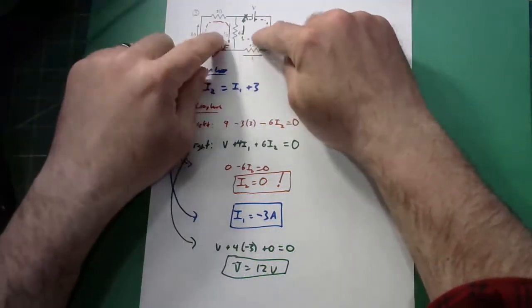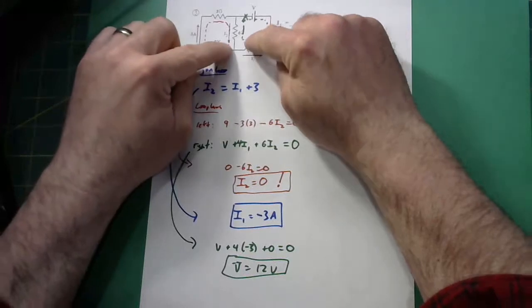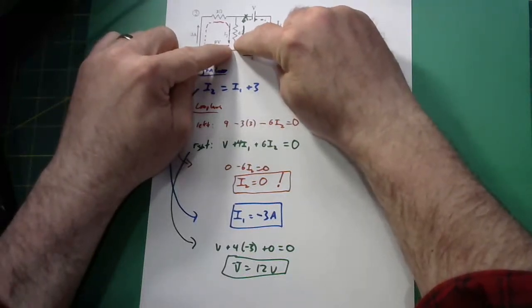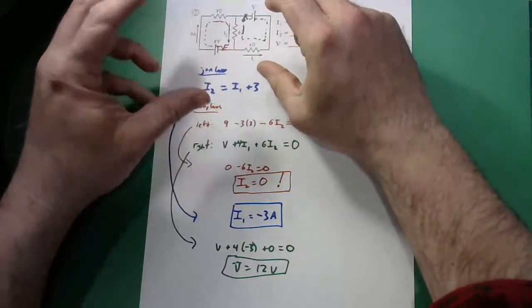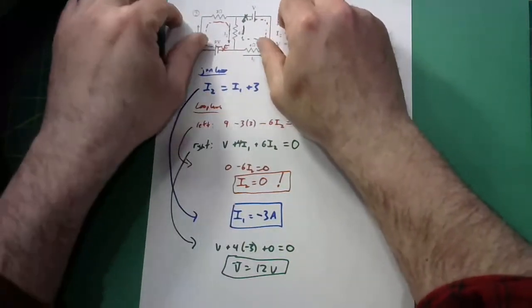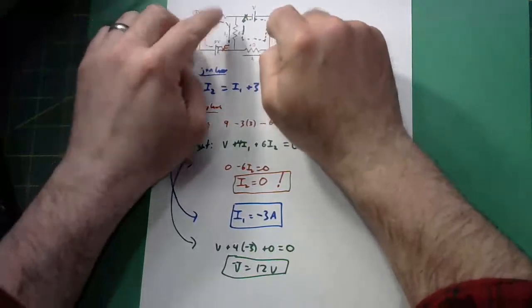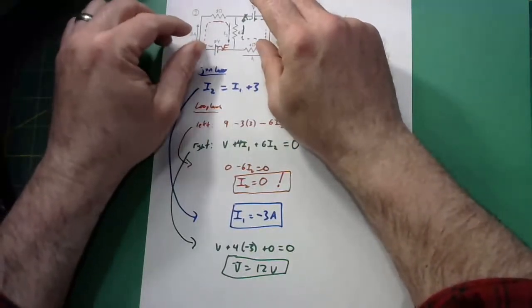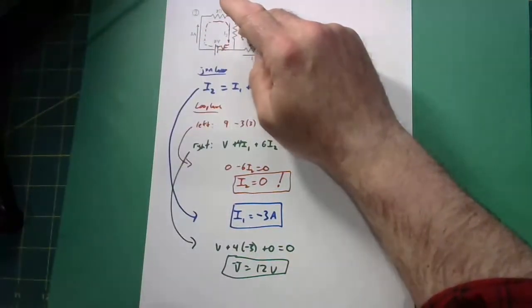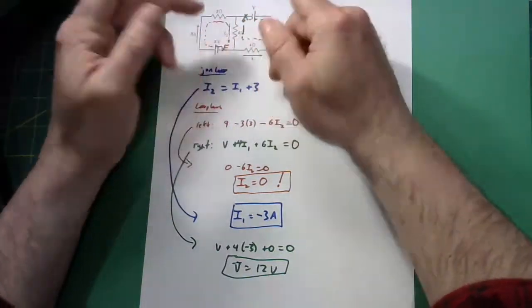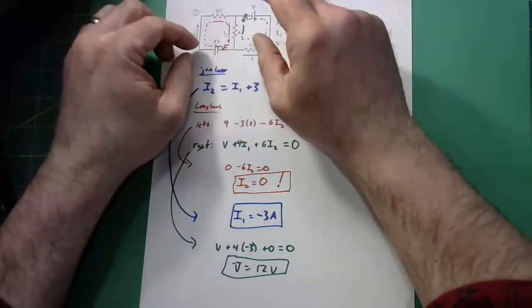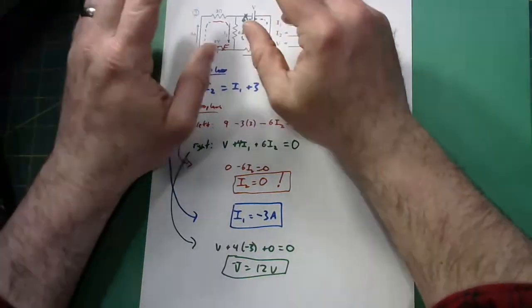So this is not a good example, but basically I'll have an ammeter here, maybe, measuring the current that's flowing through this. And when I adjust the adjustable resistance to the point that balances out the resistance on this side of the circuit to this side, the voltages balance out across here, and there's no current flowing through. Then I know I get no current through that ammeter, and I'm like, aha, I know that this value has got to be the same as this value.